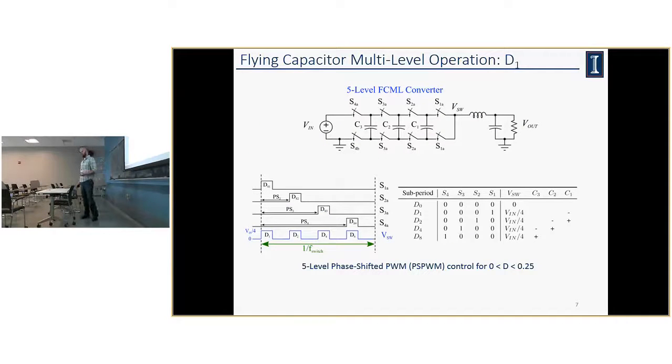Talking about the control strategy, what's typically used is phase-shifted PWM operation, and it's pretty classic, derived from some of the first papers out there. Essentially you provide 4 PWMs, each one phase-shifted evenly, all at the same duty cycle, and you get this nice operation. This is looking at the lowest level. This chart shows the output of the V-switch node, which from here forward, just think of as a buck with a PWM going into it. Over here is the charge and discharge of the capacitors, which is very important for balancing, and we'll talk about why that's important a little later.